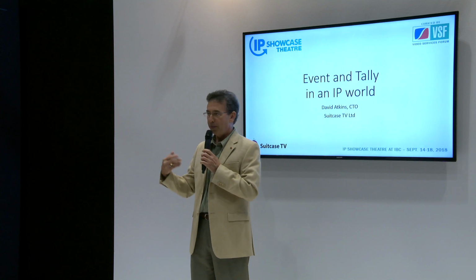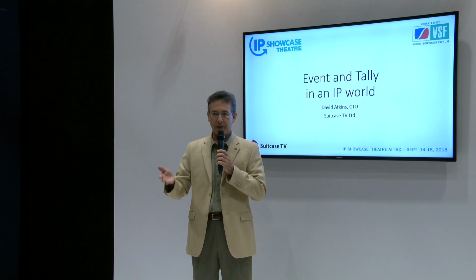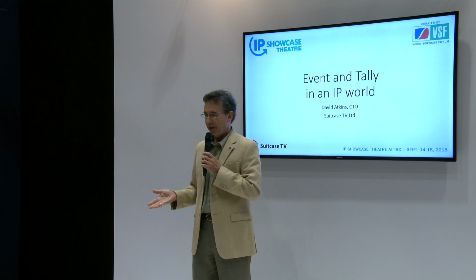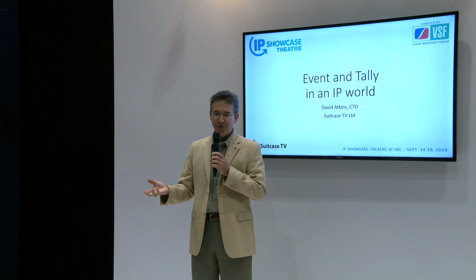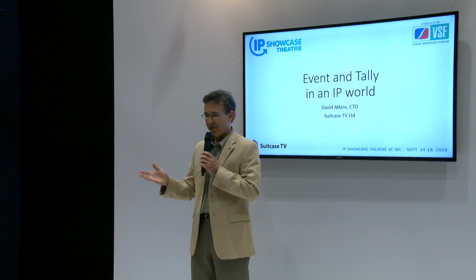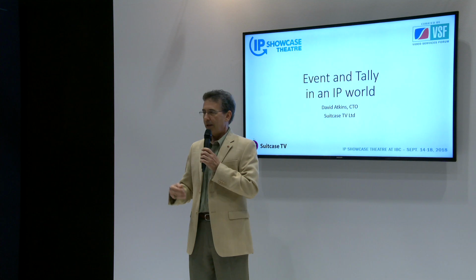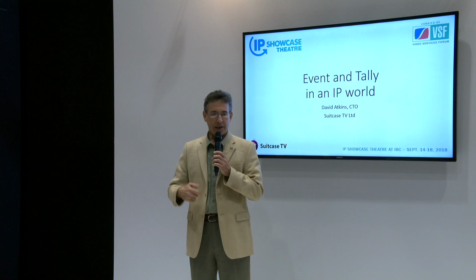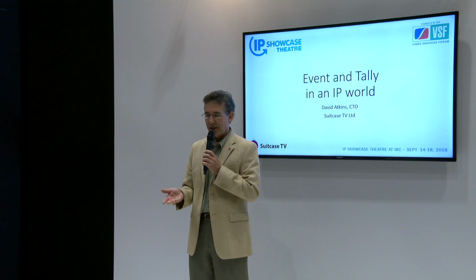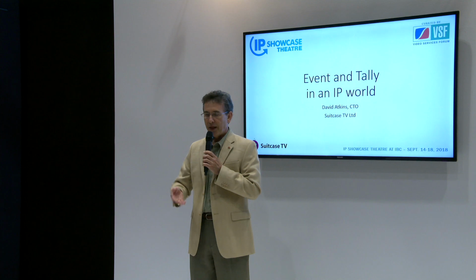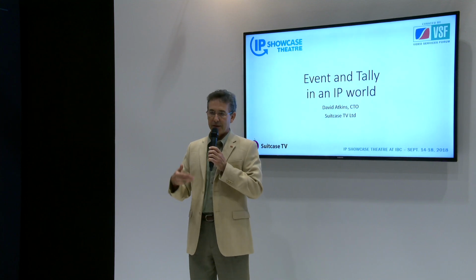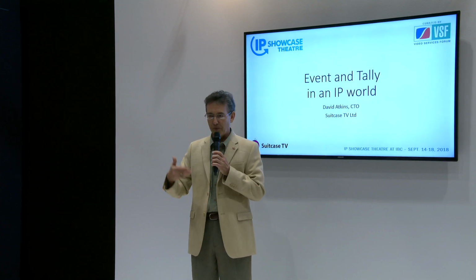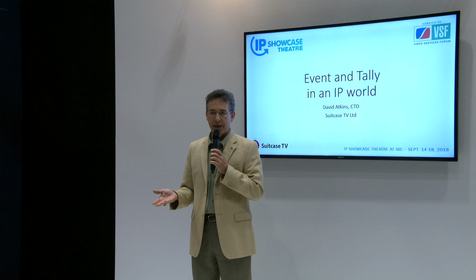You might know them as GPIs or some other function, but basically, if I push a button and I want to light the tally light on a camera, it's very easy for me to do that with wires or some sort of older computer protocol. But if I'm going to do that in an agreed common way across the industry in an IP environment based on 2110, how am I going to do that? And how do I do that in a way that scales to potentially thousands, hundreds of thousands of events that might be occurring in a large broadcast facility?